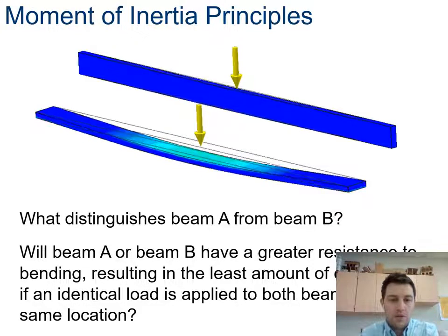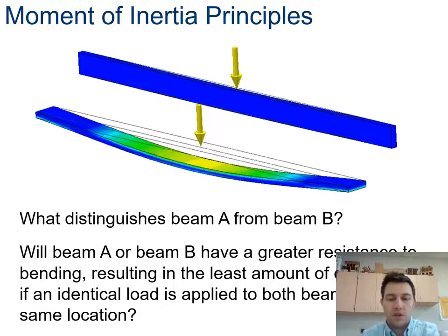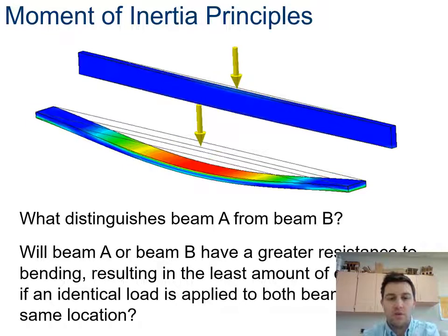If we do what's called the stress test, something you could do in Autodesk Inventor or any other CAD software, the red shows higher deformation. The plank deforms, or bends, more than the joist does, and that's because of moment of inertia.